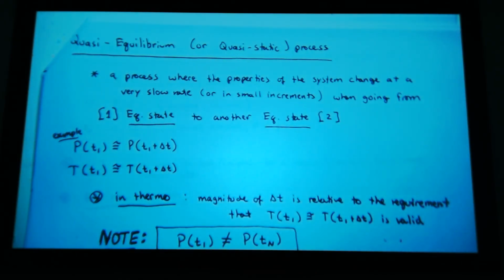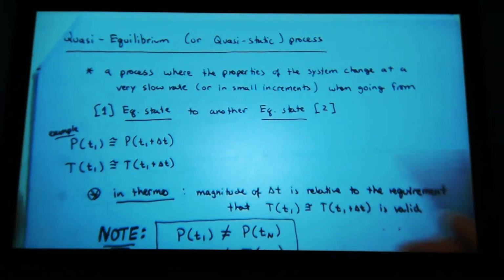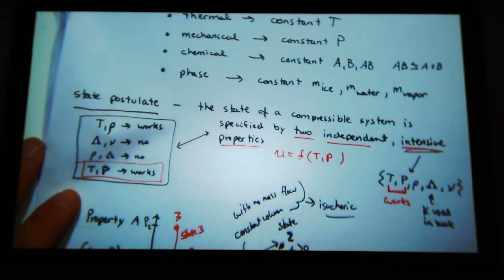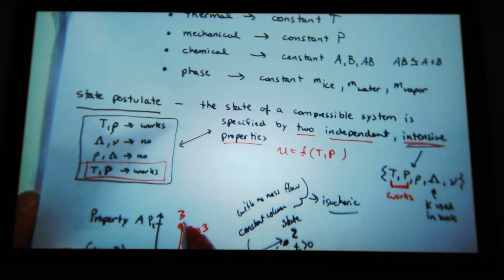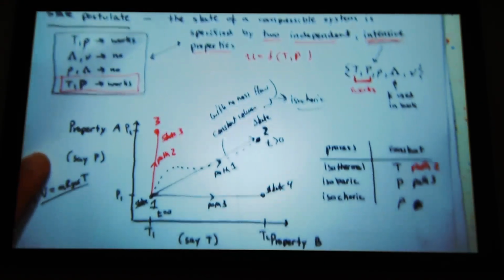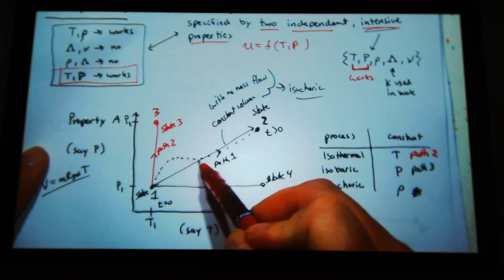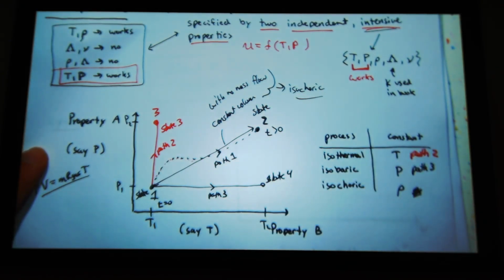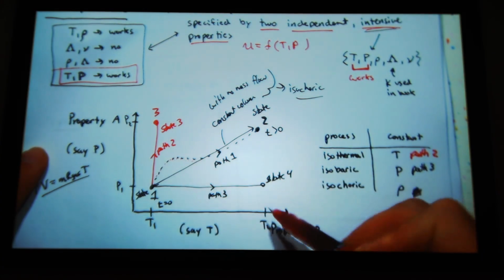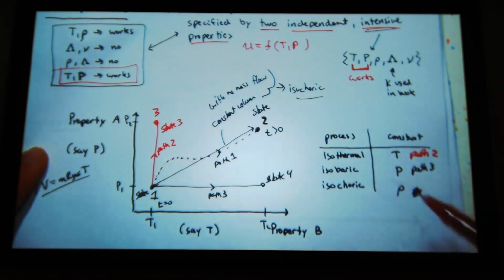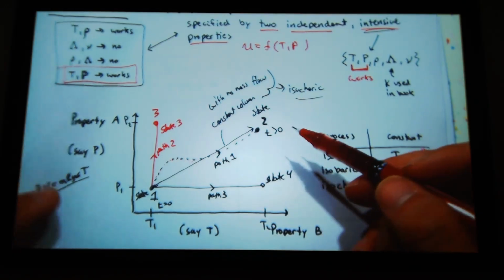So when we drew these paths, the temperature and pressure were changing. If I go back to this graph, I drew these different paths. When it's quasi-static, temperature and pressure are changing in time, because I'm going from one equilibrium state to the next equilibrium state. If I break each one of these down into substates, I would say that it was equilibrium at each substate. There are no large fluctuations in temperature and pressure, but it follows a path to change those.